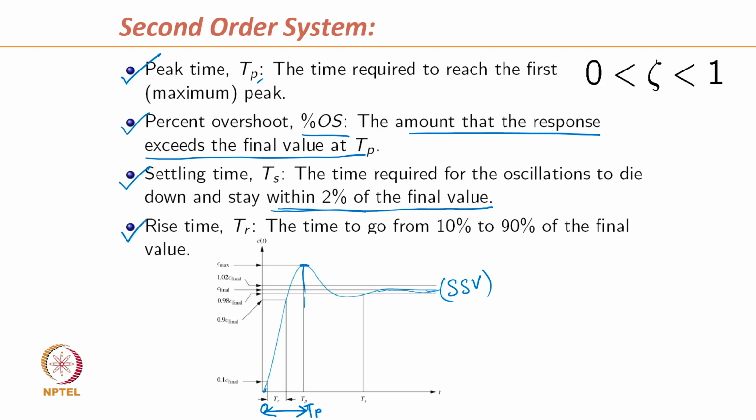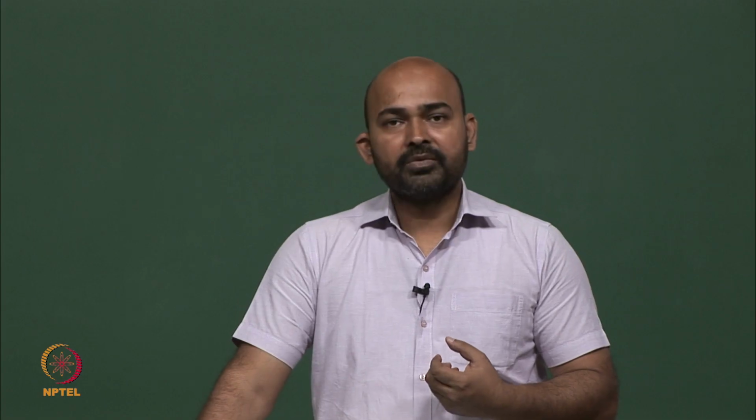Rise time means when the output is rising, how much time it takes reaching from 10% to 90% of final output. Final output means the steady state value. How much time the system output takes reaching from 10% to 90% of steady state value, that is the rise time.